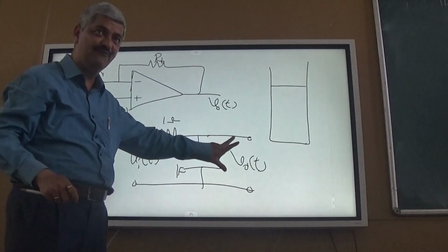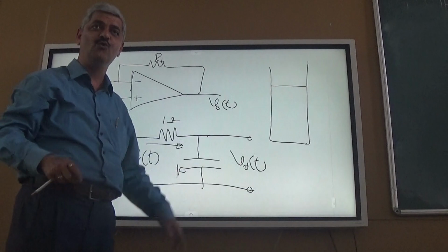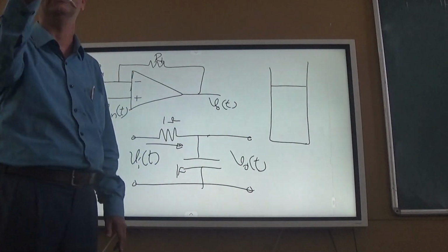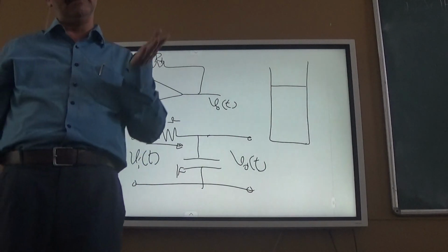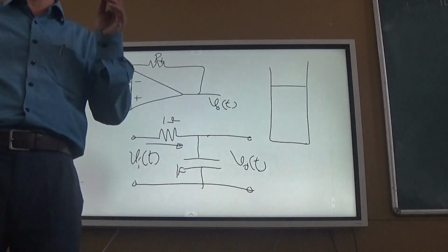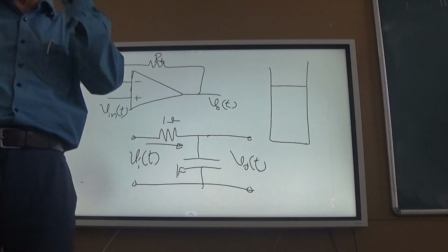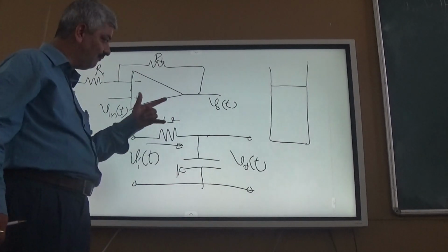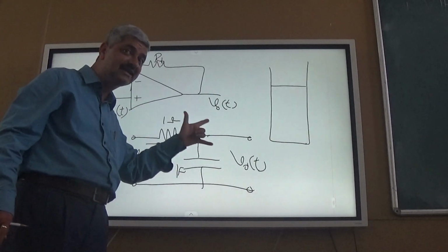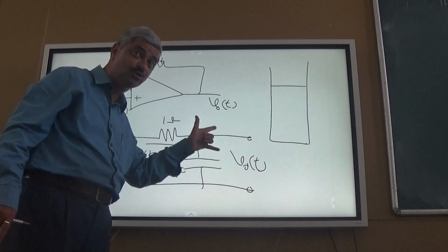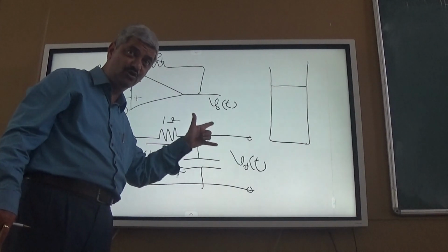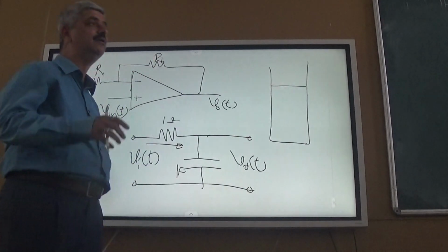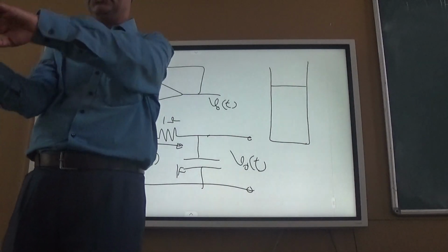So whenever you connect a voltmeter, it will draw some negligible current. So some change will definitely be there, but we must ensure that it is negligible, right? So any circuit we have, the output we state is under the condition that no current is drawn out of that. Therefore, when we want to interconnect some circuits,